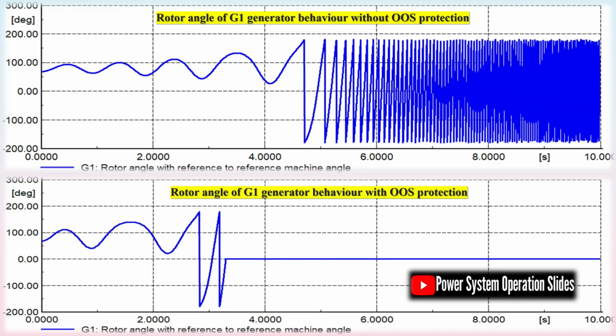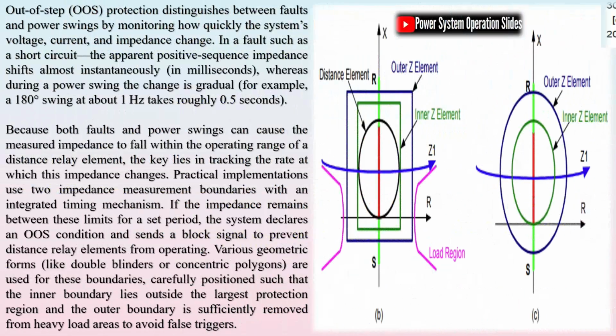Some out-of-step tripping (OST) relays provide only tripping functionality, while others also include power swing blocking (PSB) capability. The standard method for detecting an out-of-step condition involves analyzing the apparent impedance at the generator terminals. Transient stability studies help determine whether a generator will maintain synchronism under different contingencies.